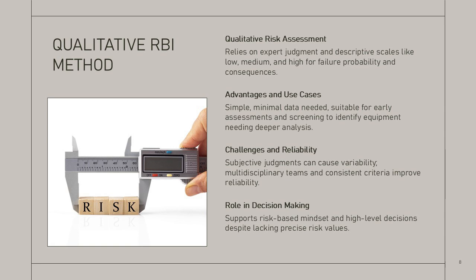Qualitative methods require minimal data and are relatively easy to implement, making them suitable for early-stage assessments, smaller facilities, or situations with limited information. They are particularly useful for screening purposes, helping to identify equipment that may require more detailed evaluation. However, the reliance on subjective judgment can introduce variability and uncertainty in the results.